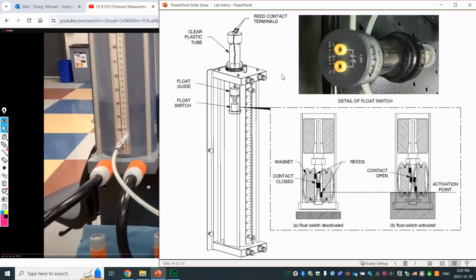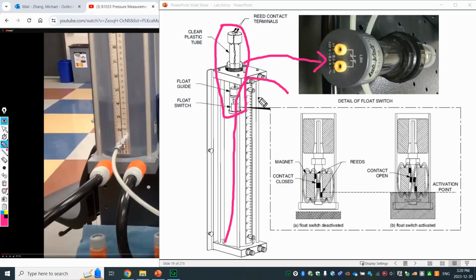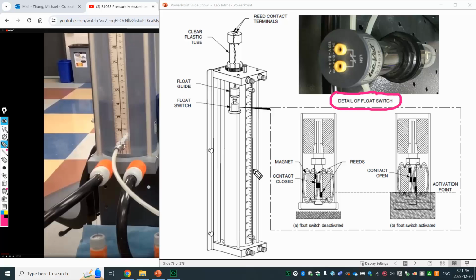This one is at the top. This reservoir on top, you see this part, has a device to check the water level. That's the real picture here. You can imagine, if we don't have any device to monitor the high level, water potentially can go up and overflow. You don't want that to happen. That's why we have to use one particular type of flow switch. Remember, we have a flow switch on the motor trainer.